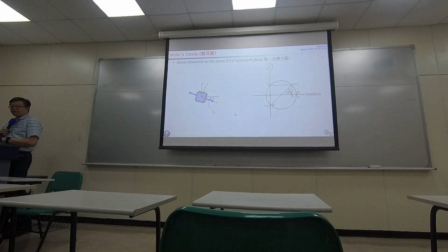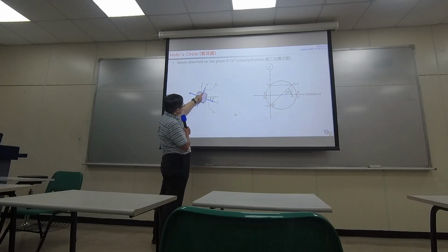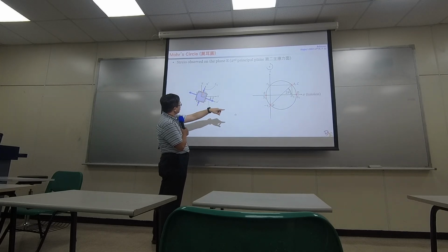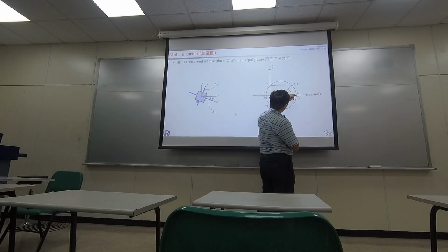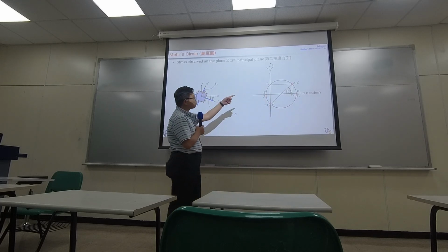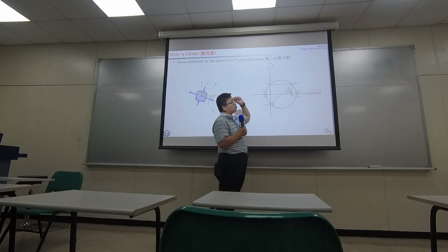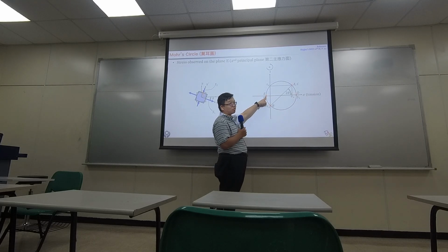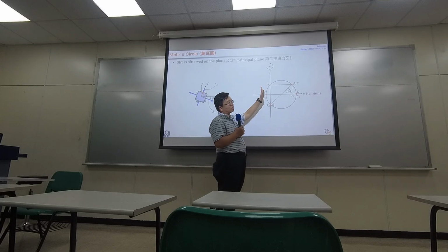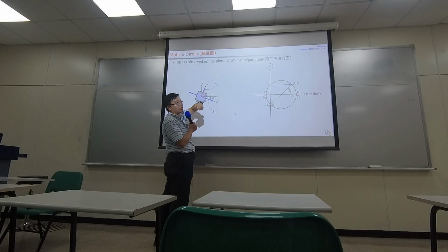Similarly, in this new coordinate system, if you from here make a turn by 90 degrees, you move on to a new point E. In a Mohr circle, you will be making a turn of 180. So now you move on to this point E. And the Mohr circle tells you, on this point E, this element is going to carry a negative normal stress, no shear stress. That's why this angle, point E, is carrying a compression stress.